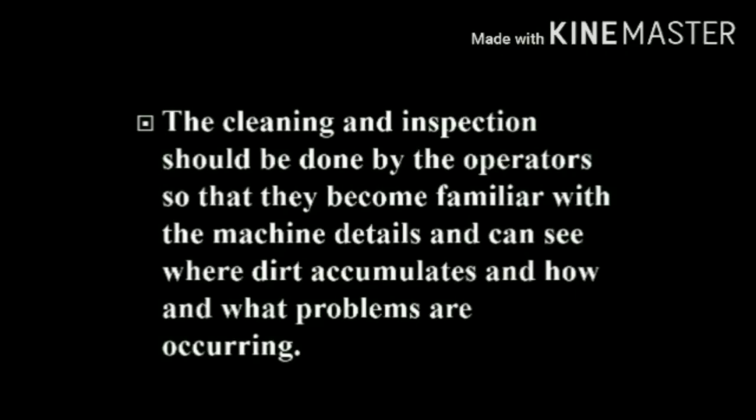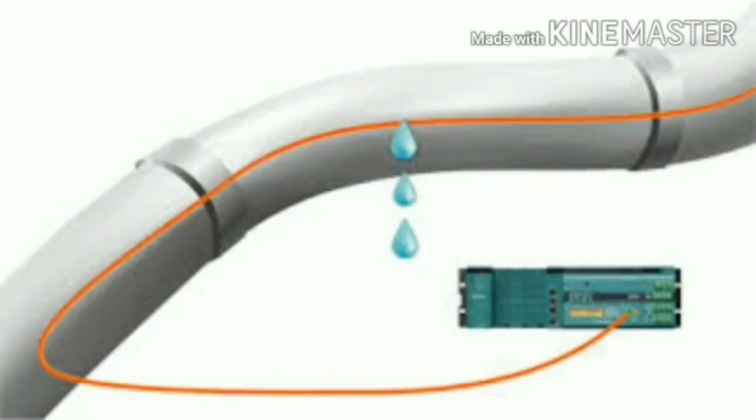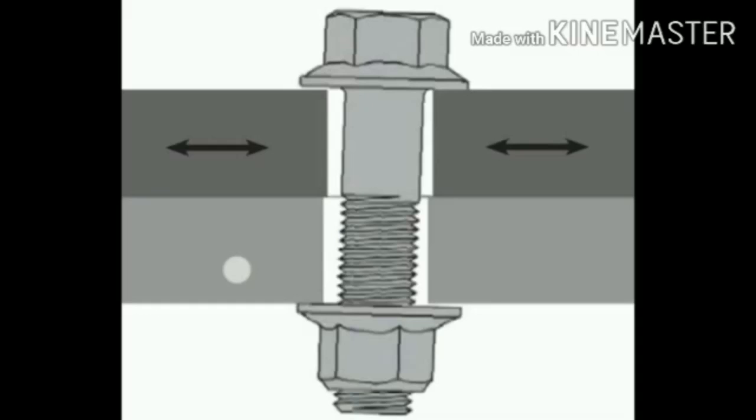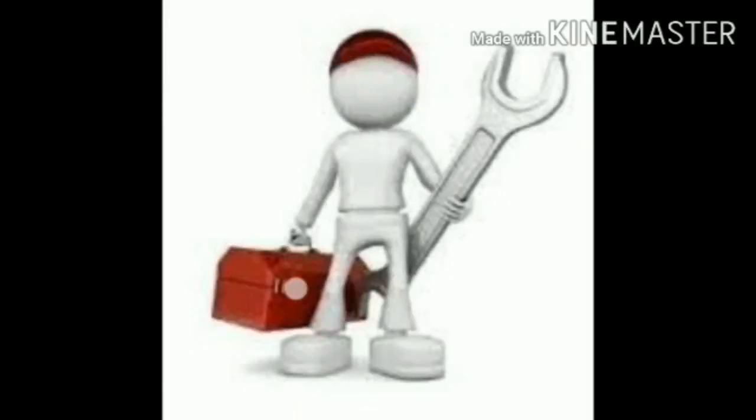Inspections that should be done on machines could include leak detection, checking of loosened bolts, lubrication inspection, correction of defective items, removal of material rest from oil or water, removal of dust and dirt, and therefore reduction of paint corrections.